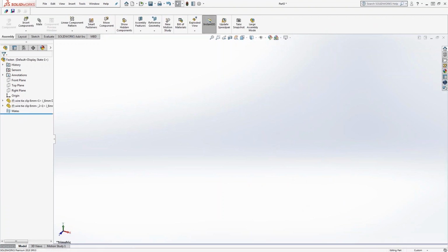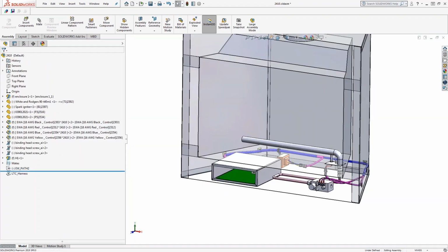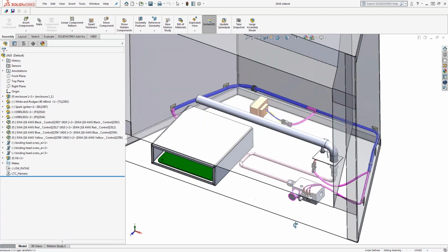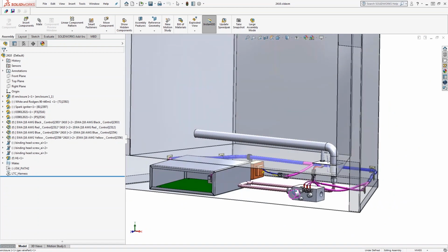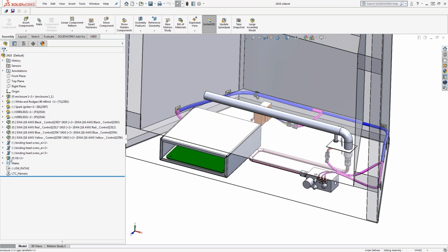All right, so you notice it's busily building SOLIDWORKS geometry, and when it is finished, we're going to have an associatively linked 3D representation of that harness built right into SOLIDWORKS. It's a dumb solid here in SOLIDWORKS. It's not directly editable, but we have this link element that's going to allow me to go back and forth if I want to update for mechanical design changes and vice versa.